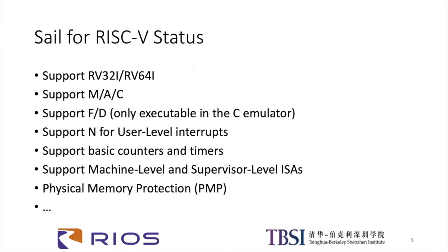Sail is being used for multiple instruction set architecture descriptions, including RISC-V. It supports primary extensions RV32I and RV64I, and standard extensions such as multiply and divide, atomic, compressed, and floating point standard extensions such as single and double precision. It supports interrupts, counters, and timers. It supports machine level and supervisor level instructions, and physical memory protection. It is complete enough to boot various operating systems.